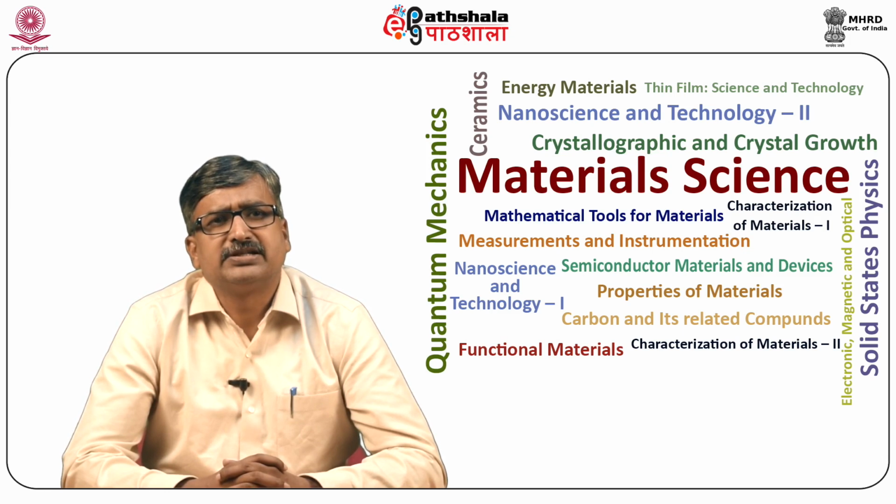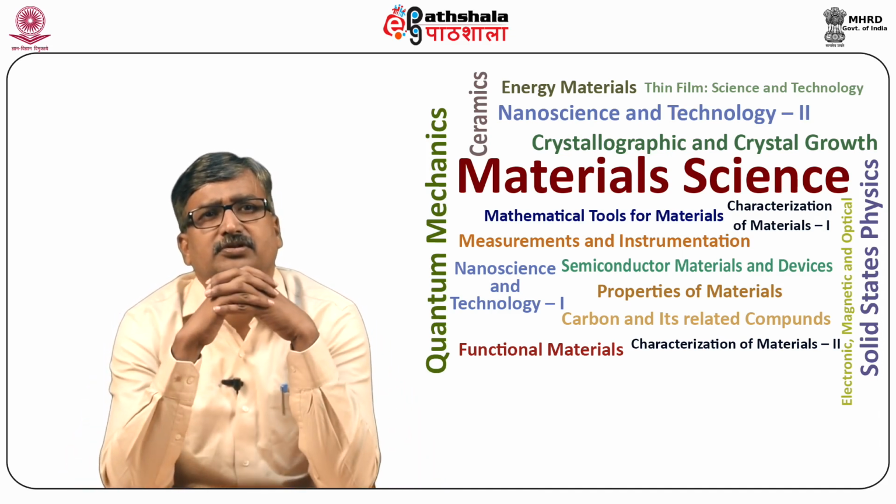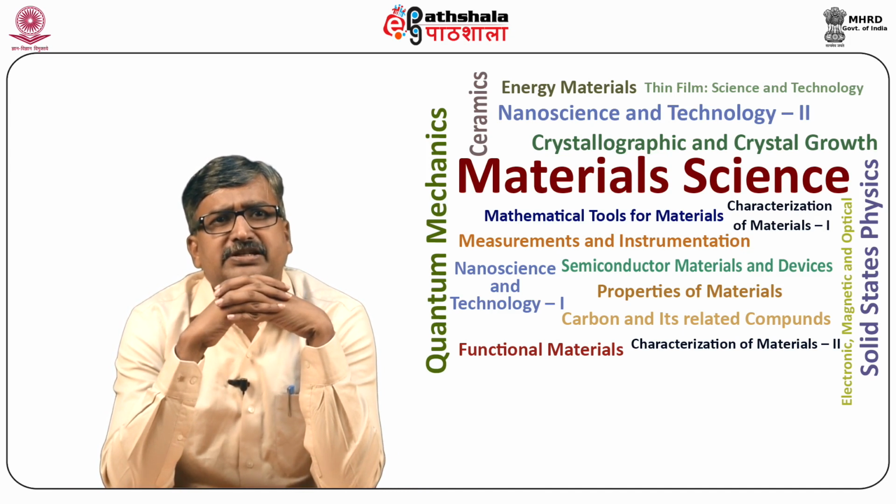Ultra-small grains, less than 100 nanometer, in nanocrystalline material can result in dramatically improved or different properties from conventional grains with sizes more than 1 micrometer, in polycrystalline or single crystal material of the same chemical composition. This is the stimulus for the tremendous appeal of these materials.